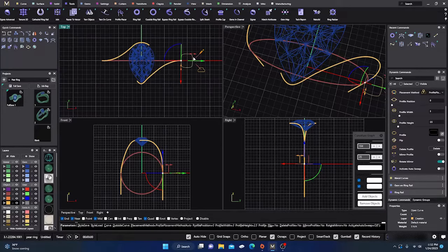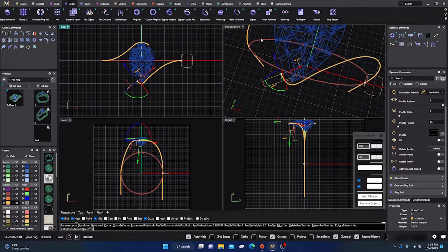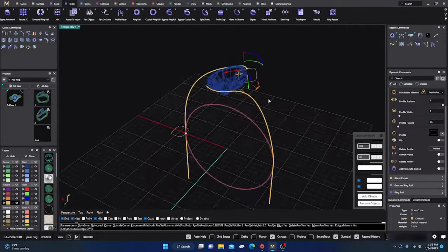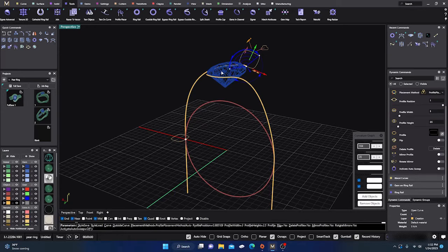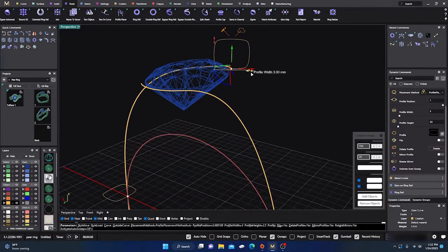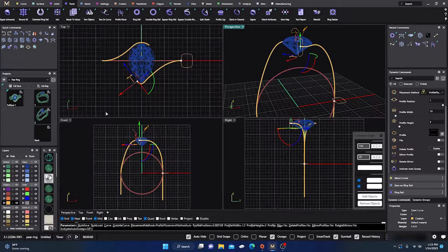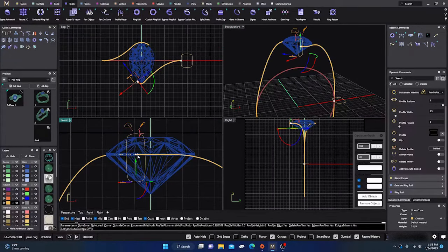We'll add another one at the top there, and swing that around so that it's facing up. We don't need it so thick up here, so we're going to take it down to about a 1.5 maybe. First we'll drag it down and then open it up to about a 3. We want it pretty close to the same height as our gem, so we'll drag that down just a little bit, somewhere around there. Should be okay, and we'll hit enter.